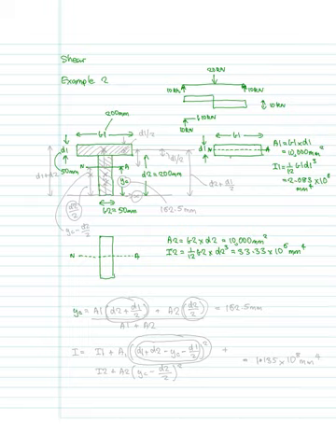So YC is going to be equal to A1, which is going to be the first area, and to that we're going to be multiplying that by D2, and we're going to be adding on to that D1 over 2.